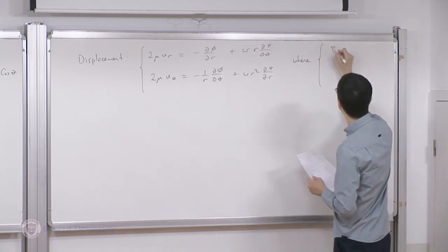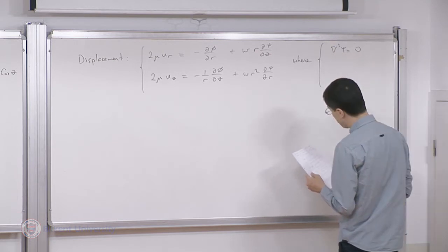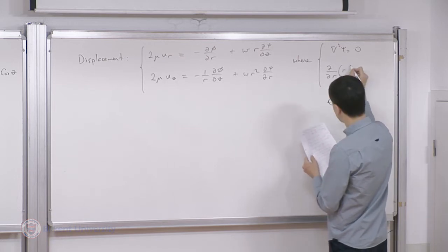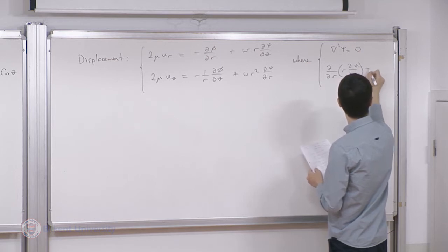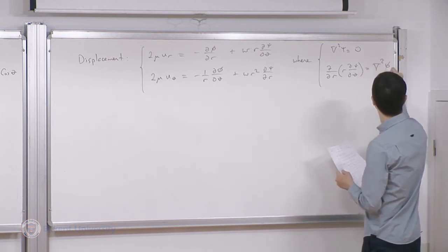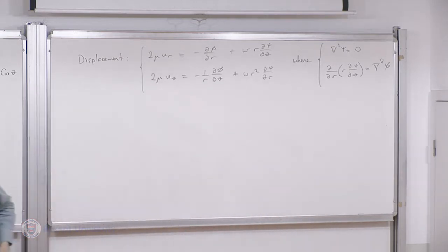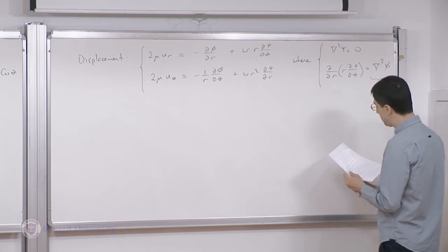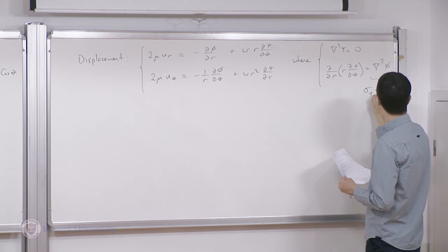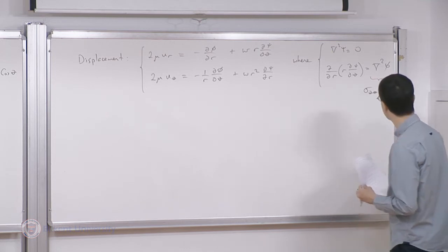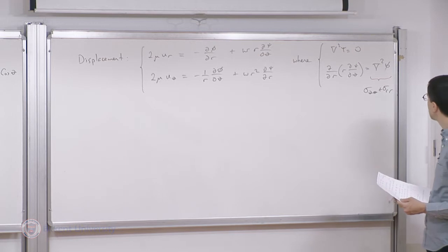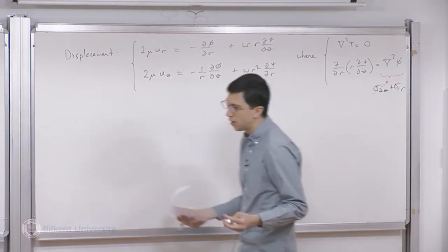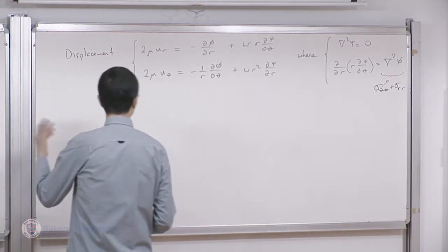And it's subject to the usual requirements. So the Laplacian of psi must be equal to 0. And eventually, there's a second condition, remember. In cylindrical coordinates, it takes this form. What I will also remind you, when you look at your notes, it's going to make your life a tiny bit easier: the Laplacian of phi, I told you last time, is equal to the sum of the diagonal stresses, and sigma theta theta is identically 0. So the Laplacian of phi is equal to sigma rr. I don't have to reevaluate it. I already have written it on the board.